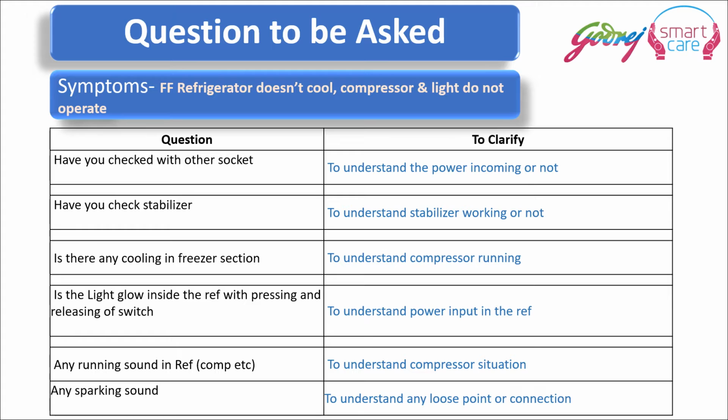One more question that we can ask them is, while pressing and releasing the door switch, does the light glow inside the refrigerator? Light glowing inside the refrigerator while pressing the door switch would be an indication that the power input circuit is complete and it's okay.